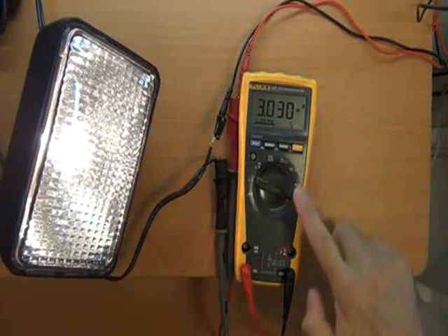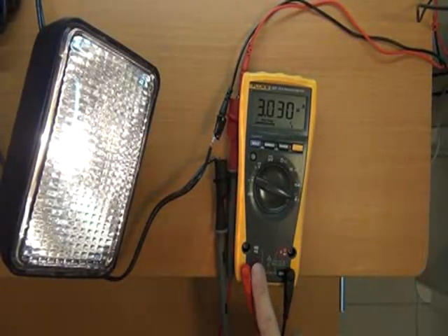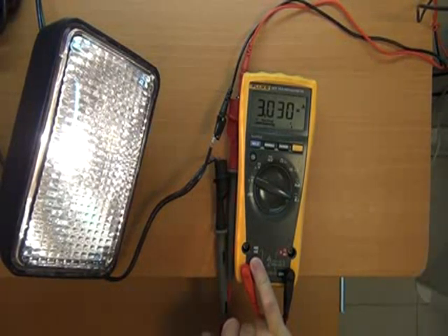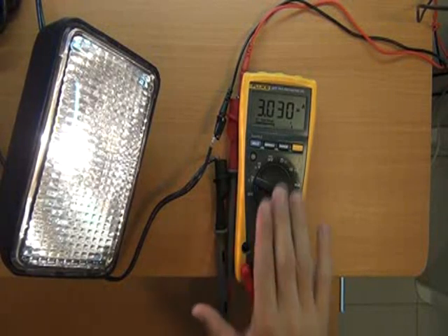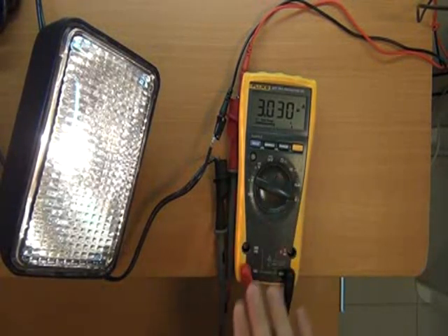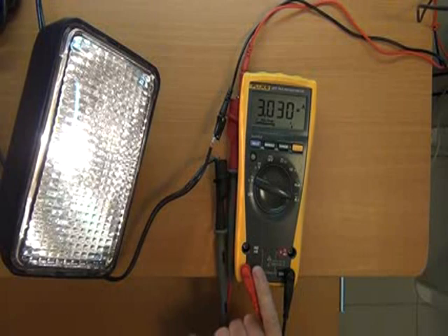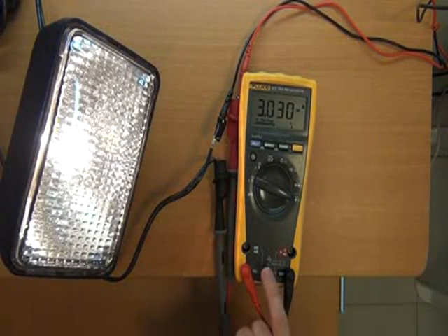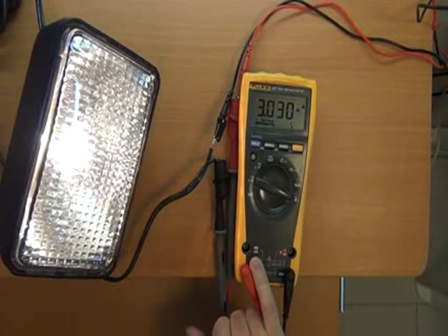Had I gone and used this 400 milliamp connection first, I'd have blown the fuse. On this multimeter, it wouldn't have caused any damage, but it certainly would have been inconvenient. You're potentially not going to have spare ceramic fast blow fuses lying around. You're well equipped if you do, otherwise you're going to have to run off to the hardware store and get the correct fuse.